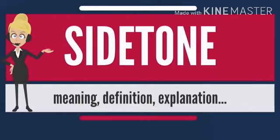Side tone is valuable for the hearing impaired. The amount of side tone typically found on landlines is 8%, and is 4% for cellular phones. Side tone can be, and often is, amplified for landline phones for the hearing impaired. In VoIP technologies such as Skype, side tone has been experimented with but has not been formally adopted by software or hardware and accessories creators. Several software packages and wiring workarounds have been developed that replicate side tone, but feedback looping remains a problem.